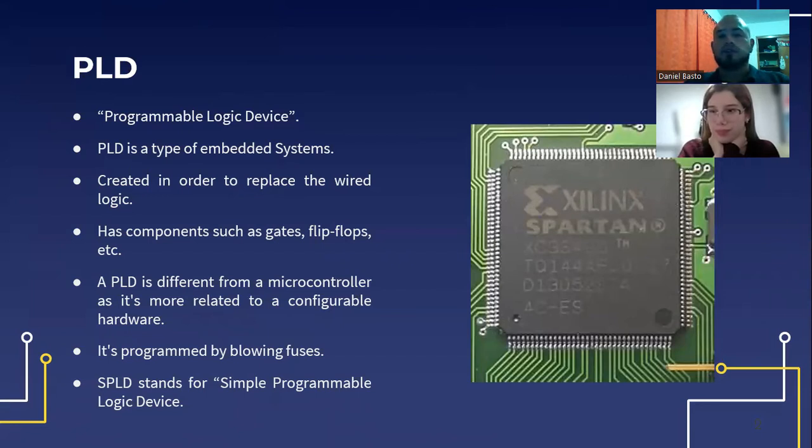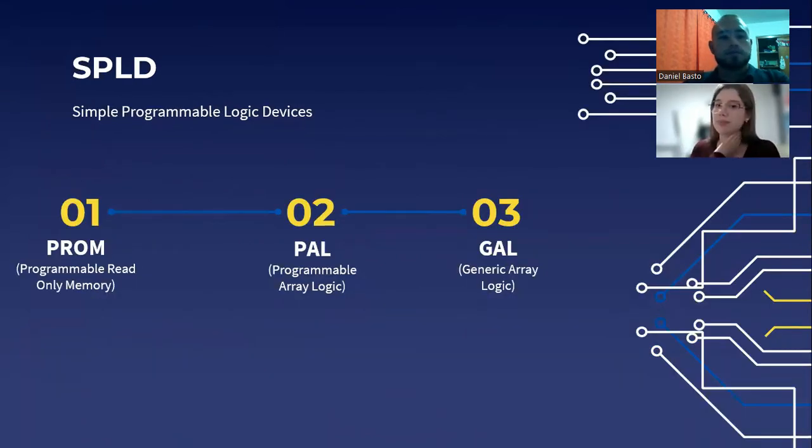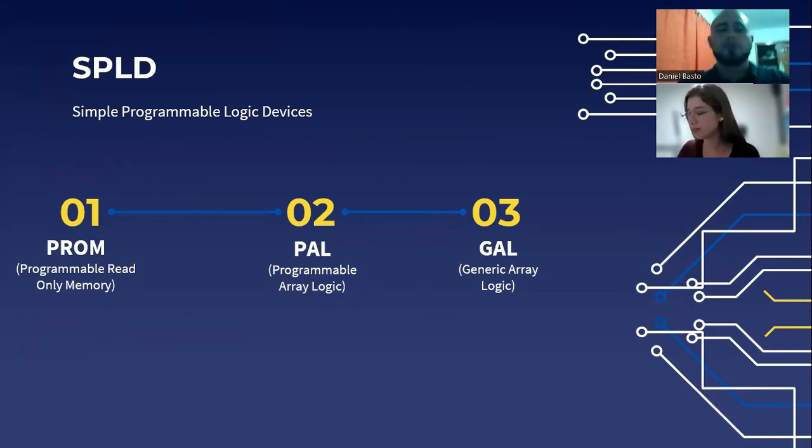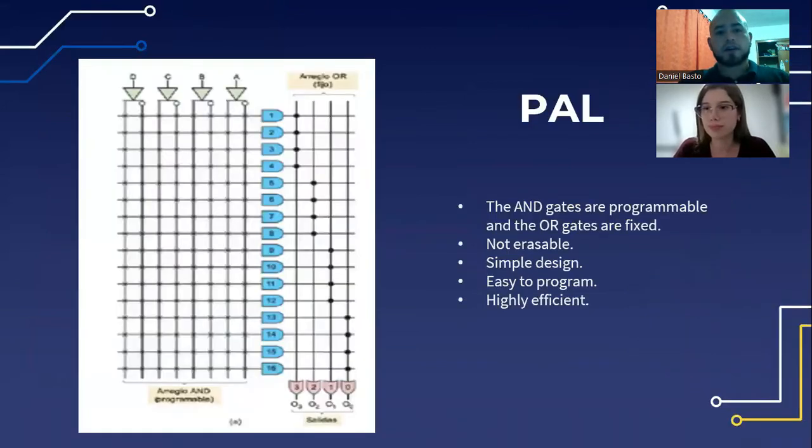SPLD stands for simple programmable logic devices. Before talking about GAL, we're going to talk quickly about PROM and PAL. A PROM is a programmable read-only memory, and a PAL is a programmable array logic. In PAL, the AND gates are programmable and the OR gates are fixed.